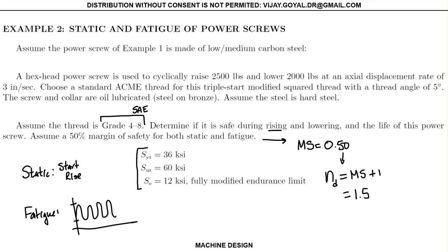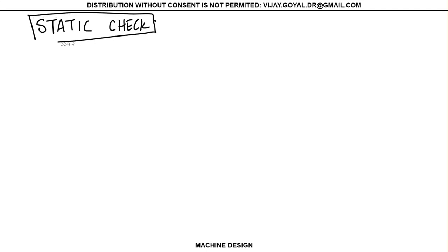The first thing you do in the problem is a static analysis. That's the very first thing we do. Static is the static check. I cannot emphasize enough, don't do fatigue until you make sure you're safe in static. The fact that it's safe in fatigue doesn't mean it will be safe for a static load, and you want to make sure that both are correct.